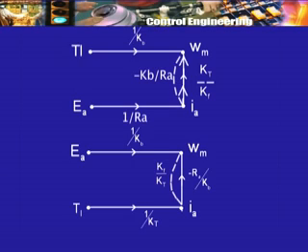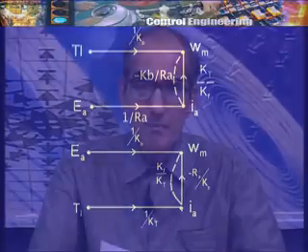In one case, Ia to omega m it is KT by KF, in the other case omega m to Ia it is KF by KT. Similarly, from omega m to Ia it is minus KB by RA, from Ia to omega m it is minus RA by KB. So the transmittances are just the reciprocals, they are not the same. Well, that has happened because we solve the equation for one or the other, depending on that one transmittance appears or its reciprocal. But in either case we have a loop.